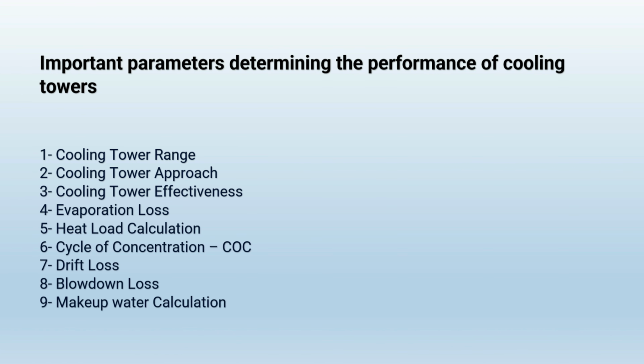Today we will discuss the important parameters determining the performance of cooling towers like cooling tower range, cooling tower approach, cooling tower effectiveness, evaporation loss, heat load calculation, cycle of concentration that is COC, drift loss, blowdown loss, makeup water calculation, and finally we'll know the most common reason for low cooling tower efficiency.